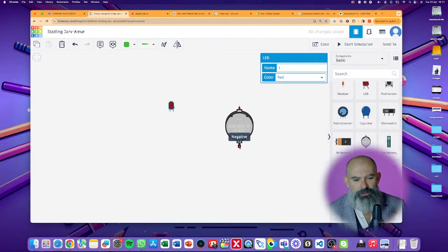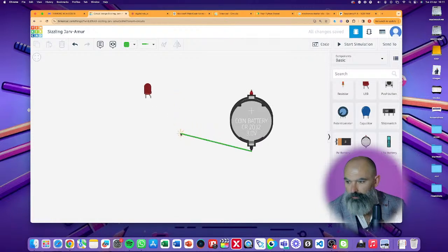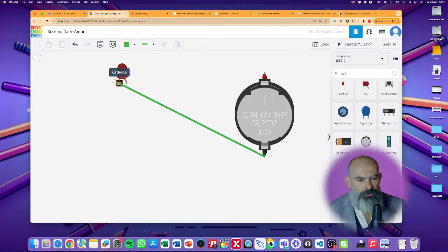The next thing that we can do is I'm going to deliberately join these up in the wrong direction. Now, this is a place where you can get really stuck really quickly. When you're on tinkercad.com/circuits in this example, if I was to click at the end here to join this up to this battery, I can click and then I can click again on the ends. But if I accidentally, and I'll try and zoom in a little bit more on this so we can see a bit more clearly here, you can see that it's kind of flashing around, it's having a look. It wants to join to that, and it says anode and cathode.